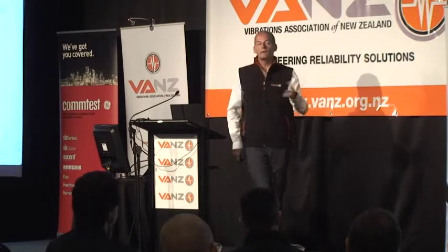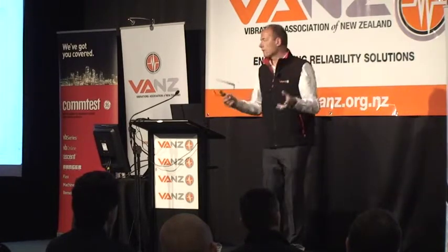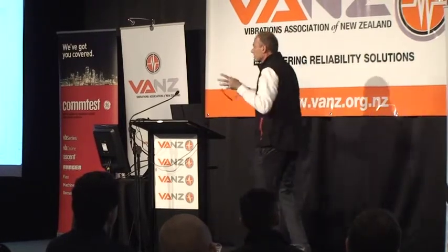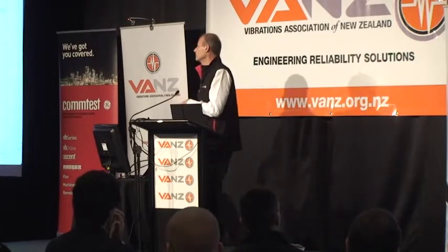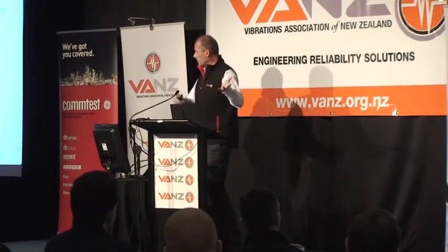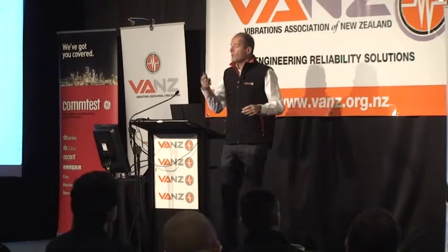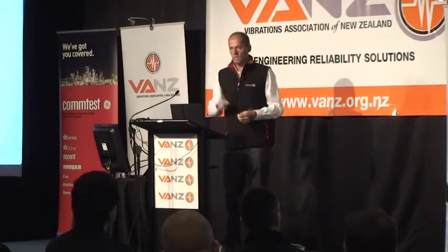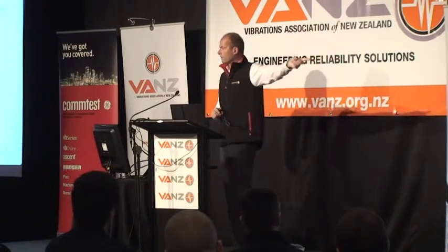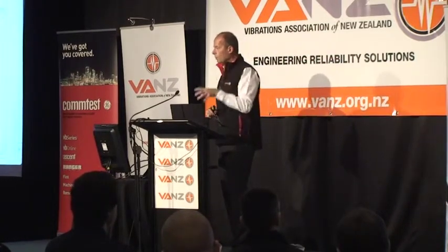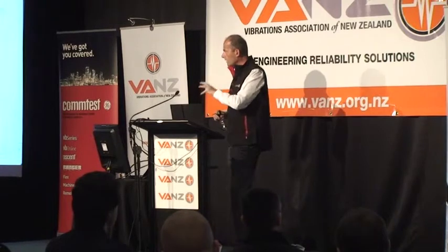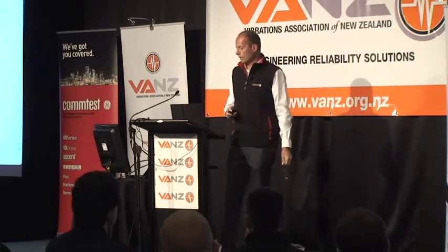So if there was any wear, we would see metal particles shearing off, and we can look at that. We can even look at the size and shape of those particles to see what condition the equipment is in. So, if you had some critical gearboxes, vibration analysis is great, but you'd be crazy if you're not doing this. Not only oil analysis, but wear particle analysis, looking at the particles themselves and learning from that.